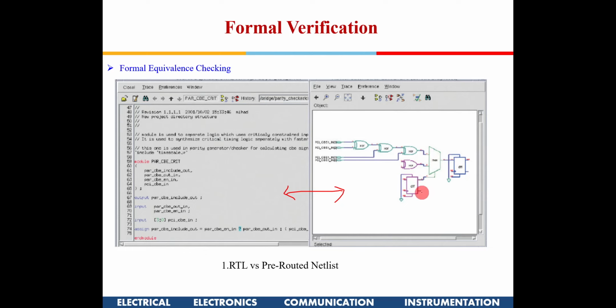Manually, because once it is generated, you might feel this is not better. Your target is maybe speed of operation, and although you have given speed as your goal, once the tool has picked up this particular module, you can see from your experience that this particular mux, I would want to replace with a faster one. So I'll replace it with a faster one. This was initially generated automatically, and now you have done some optimization here.